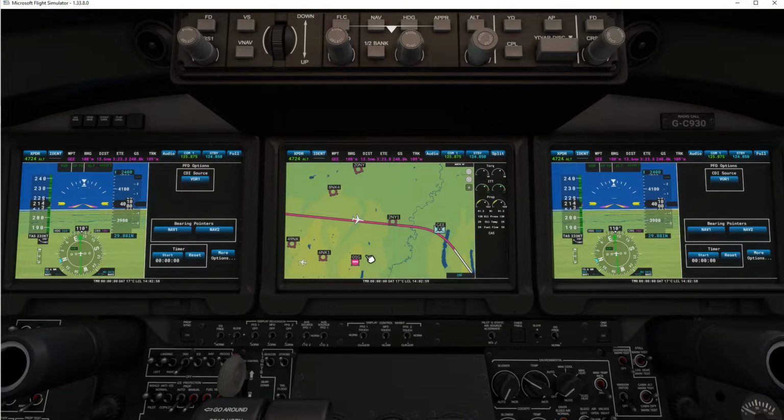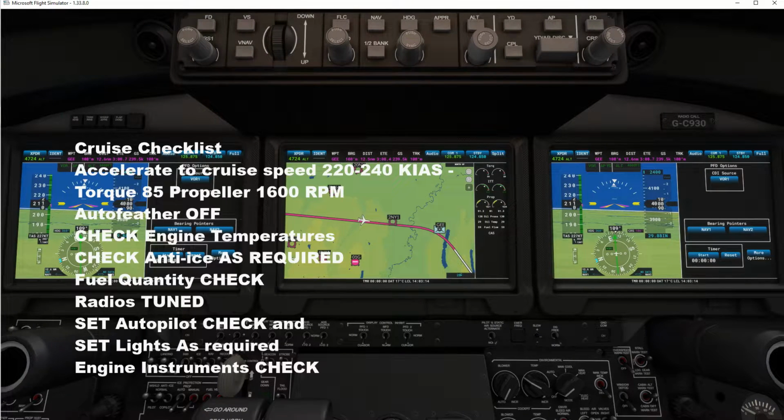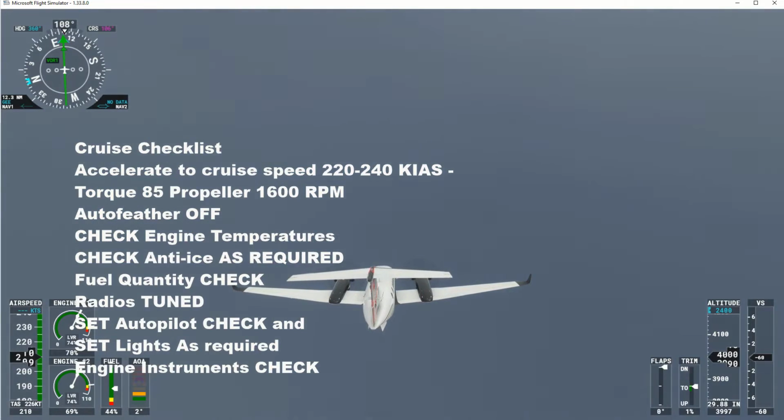And as we approach it, on the split screen there on your left of the primary flight display, I'm going to switch to VOR-2, because in VOR-2 I have programmed in 157 magnetic on the course that we're going to take.